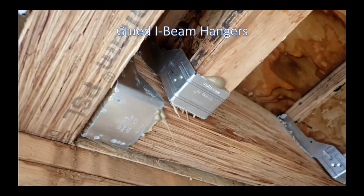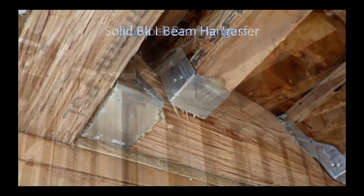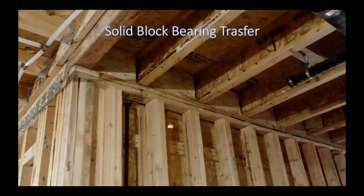And you can see the parallel strand lumber, the PSL, excellent material that they use plenty of. Because there's a lot of compression load coming from the upper story walls to transfer down to the lower story, they use a lot of solid blocking between the floor joists to transfer the upper wall loads down to the lower walls right through the whole system. A very common, simple way of transferring forces through the building down the stories.